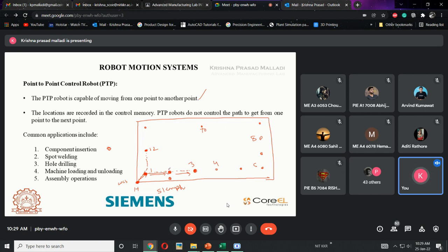Now the spot was done, again the robot will pick up speed and move in some direction at the 5 kmph speed, and it will reduce when coming to this point, coming to the 0 position, and the spot is performed. It will do the same thing, again coming to the 0 location, again the spot.